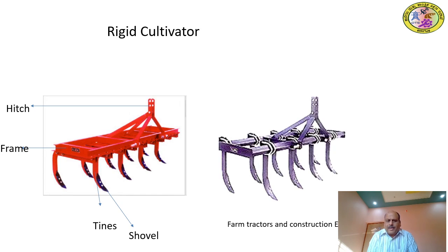In the hydraulic system there is a top link, and we connect this hitch point to that top link. The other two ends are connected elsewhere. Just see, the steel rod is there, and it is not painted in the figure, on the left side. Before the hitch is connected, the attachment is given, so those points are connected to the left and right arm of the hydraulic system.